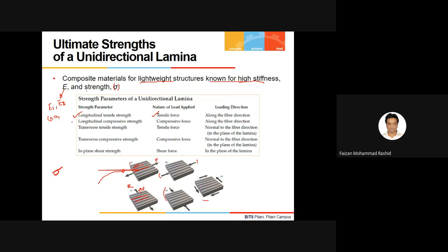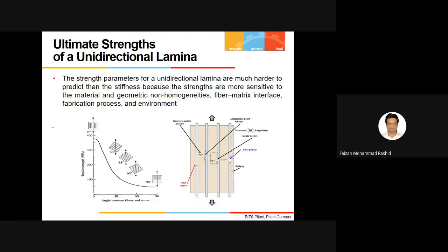So we have to see all the critical stress values in all these 5 different modes of failure, we can say, for my composite material. So let's see how much we can do here. You see here, I told you, when the fibers are aligned like this one and you are pulling the load, it is like this. And when the fibers are aligned along the direction of your loading direction, means the load is aligned along that fiber direction.